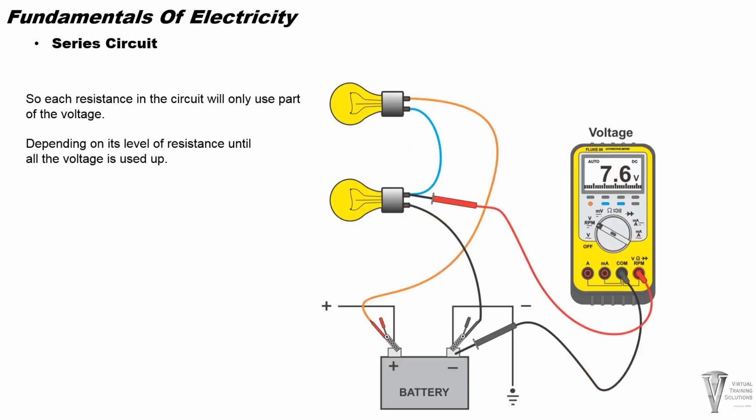We already measured voltage before, so the first step to resistance is to prove the principle. There was 14.3 volts applied. A simple voltage check shows 7.6 volts after the resistance.